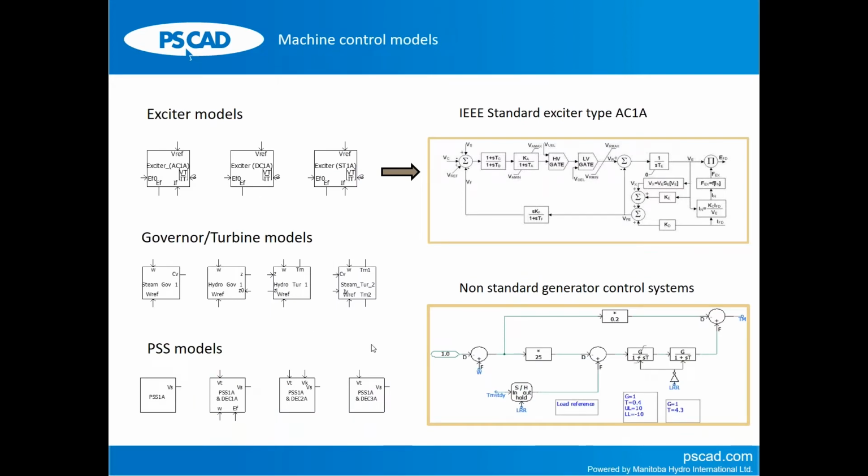Synchronous machines always work together with exciter and governor models, and sometimes power system stabilizer models. In our master library, we have provided almost all standard exciter, governor, and PSS models, the standard IEEE models.